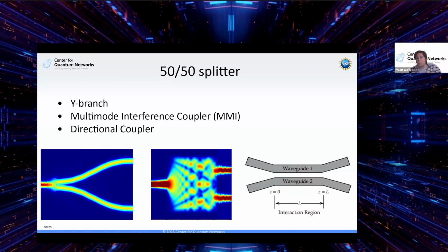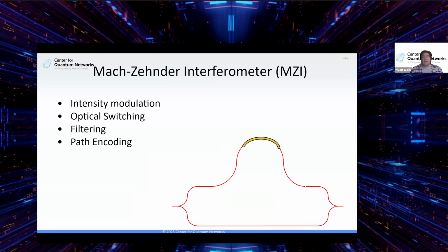And so it can bounce back and forth for a long time, so you need to make sure, from all your parameters, things like your effective index, how much coupling is going on, and how far away your waveguides are, that you optimize what that coupling length is. That way, only 50% of the light goes over to waveguide 2, and then they go away from each other again. So these are things to think about. All right. So for our next idea, okay, I can split it up 50-50 in all those ways.